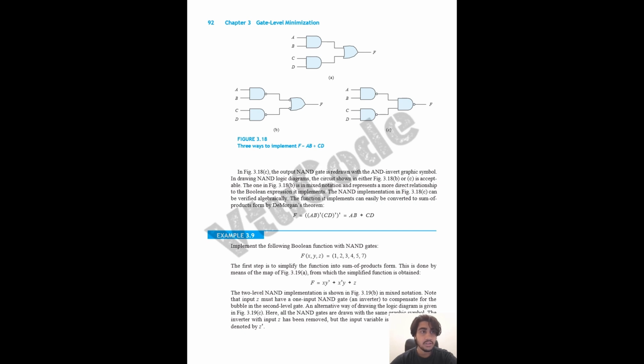So this was about K-map applications, advantages, what is K-map, what are the different types of K-map, a 4 variable more importantly, in the concept of binary coding, how we write it, the cells, the number of cells, how would we find the number of cells, 2 to the power of n, those things, draw the truth table, and then a logic circuit. Simplification is based on common factors. How do we group it? Based on quads, that is an oct, quad or a pair. This is all about K-map.